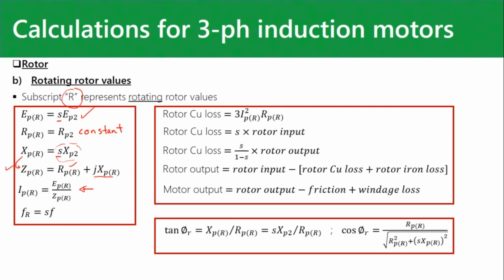And the frequency of those waveforms in the rotor conductors, FR, when it's rotating, is S times the frequency. This is typically your 50 hertz, say, supply frequency. So in the stator, this will be F, would be the frequency, and in the rotor, FR would be the frequency.